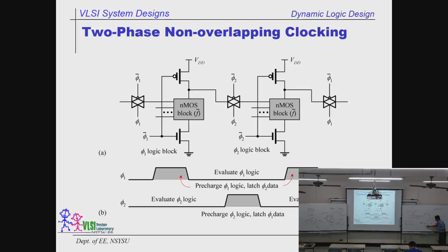There's a short delay here, there's a long delay, and they're not matched. So if you simply use a single clock, drive one buffer, and the other one is an inverter, trying to generate 2 non-overlapping clocks, I guarantee they will fail. It's impossible. I have some special circuit for you, and it is widely used.